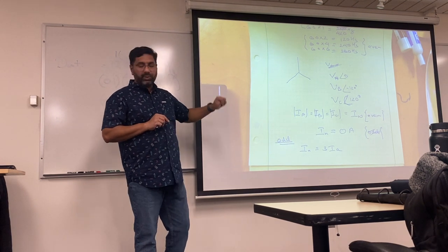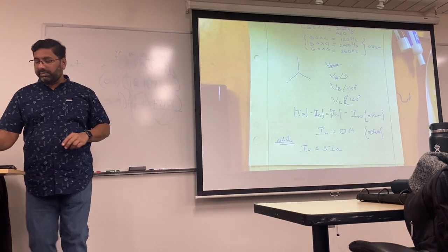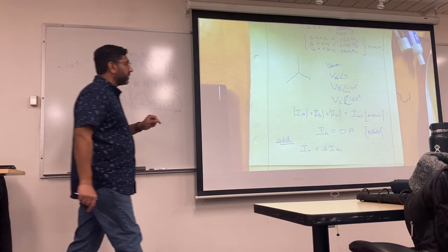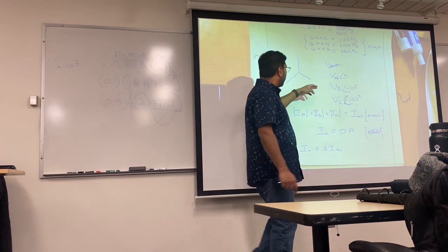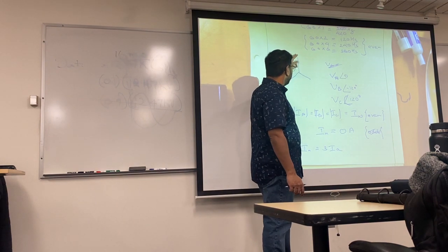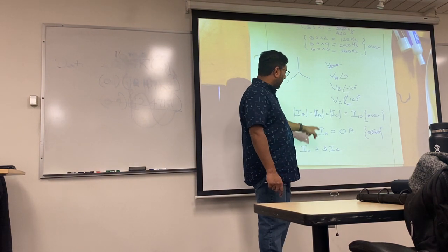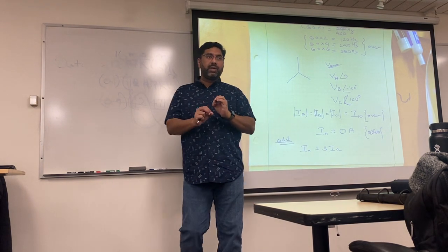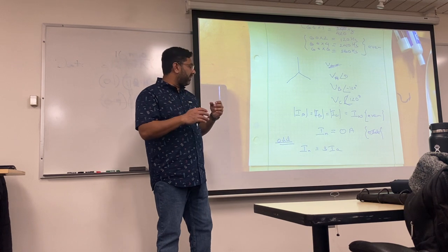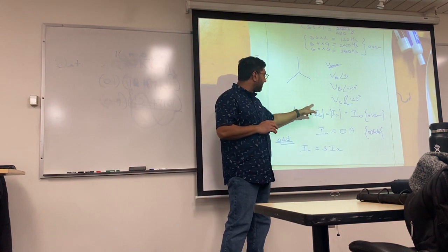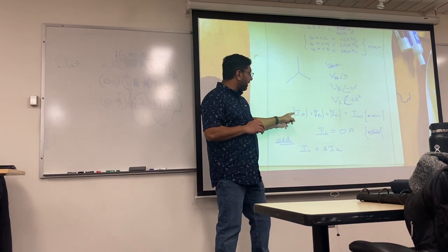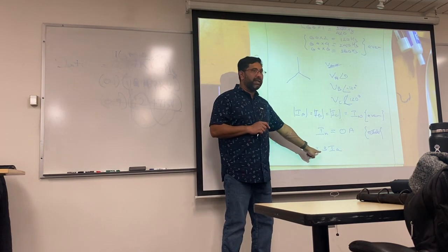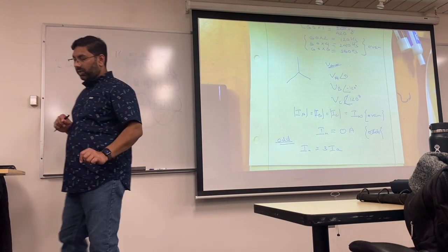Expect them to have a fourth wire. The fourth wire is there because there is going to be a neutral current, and that neutral current is going to be 3 times, I'm just picking this as IA for now, 3 times IA. We just did a wire sizing calculation. So if you end up with 50 amps for your phase current, don't just blindly pick 50 amps for your neutral. You actually have to go 3 times the phase current for your neutral.